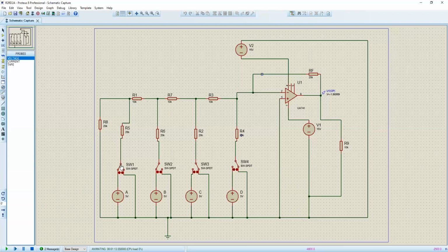So we can also control the step size by changing the R values and feedback resistor values. In the previous example we had a step size of 0.5 volt, but in this experiment we have a step size of 0.625 volt. So it actually gives us more resolution, and the output won't be congested in the graph in this experiment.